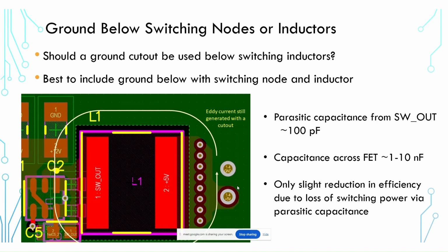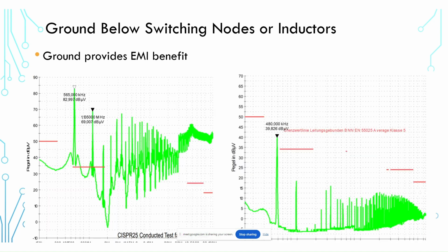Now, I think all of those issues are offset by the fact that when you do have a faster FET and you do have faster edge rate, you are going to have greater shielding for radiated emissions in this design and greater shielding for crosstalk into nearby analog or digital interfaces when you include this ground plane. This is because the magnetic field will not be able to radiate, or pass, I should say, through this cutout through the entire board and then be observed around the PCB.